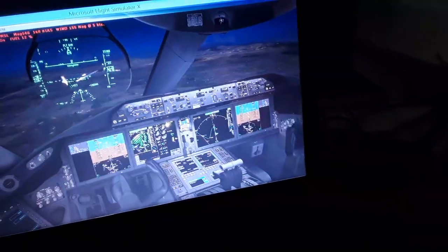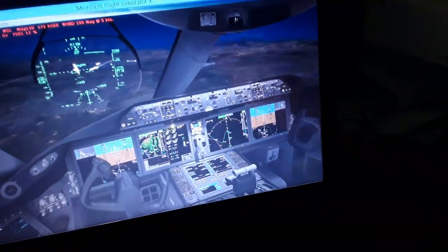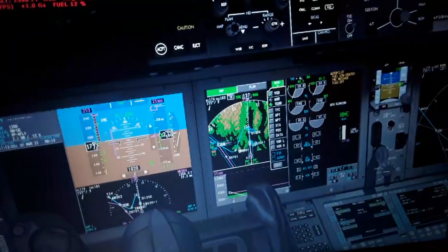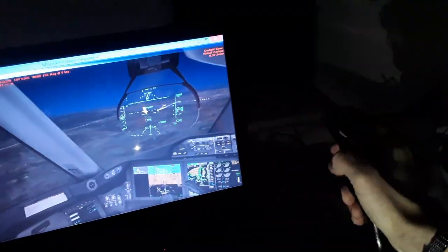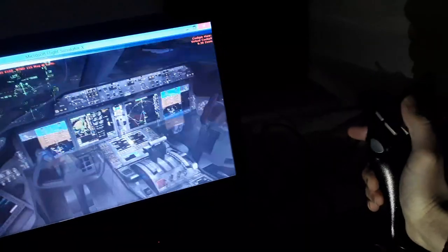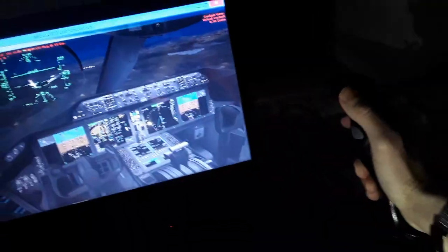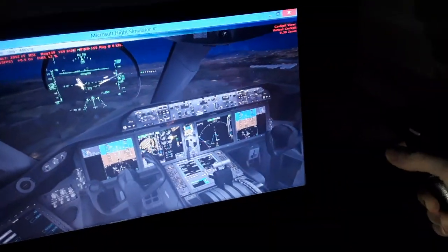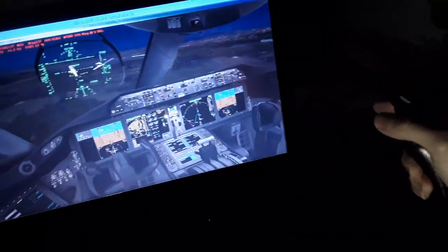Add a little bit more airspeed over here. We have the side wind and wind gust. We have also the LSZH localizer over here. We need to follow the localizer for landing. So we need only to align with the horizontal over here. As you can see, a little bit of rudder. You have some side wind, some wind gust over here. Increase also the airspeed a little bit as we descend, and increase the rate of descent a little bit.